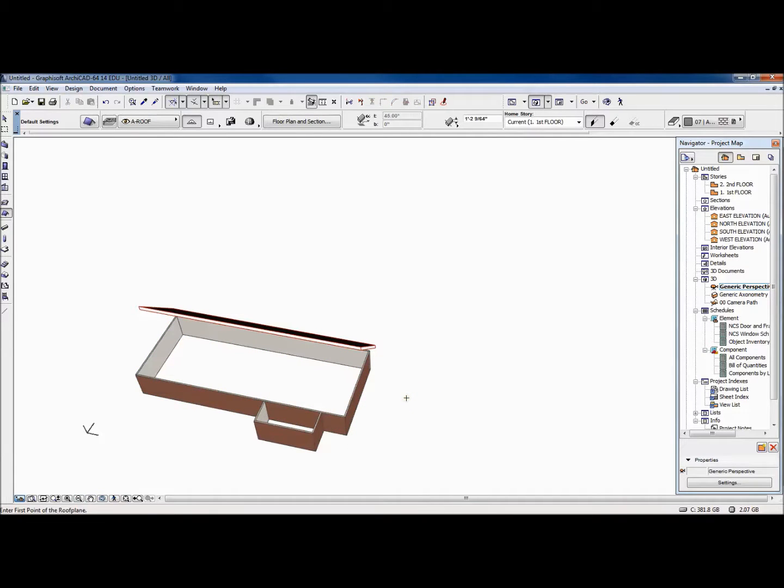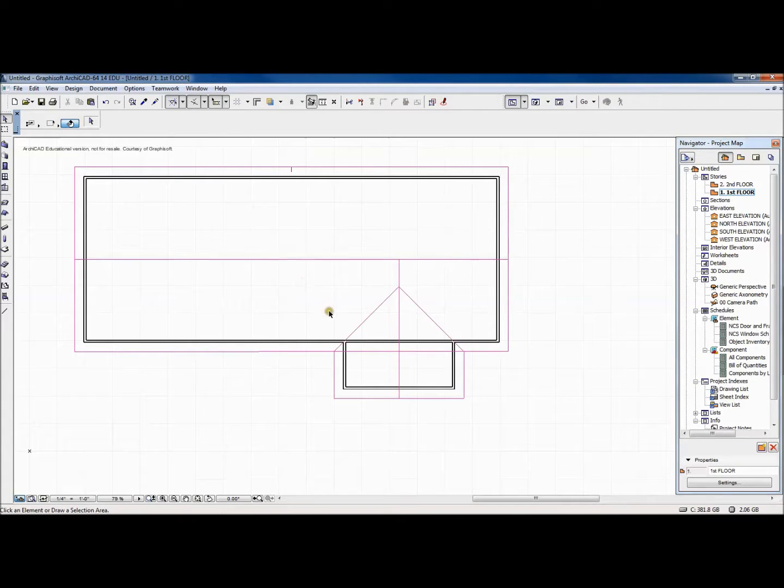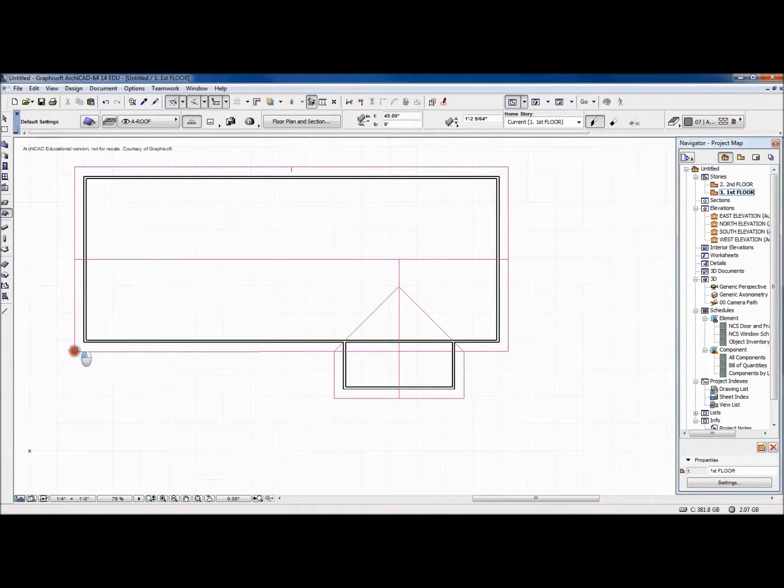And let me escape that, and we'll go back to F2, and now let's build this section. And so what I'm going to do again, we'll click this build roof tool, and we're still going to pivot across this entire front section. We do want that to come back to the ridge, but here's where it gets fun. What we need to do is trace the actual perimeter. So do you see how it changes? Where it comes down those valleys, back up the gable, and to close it.